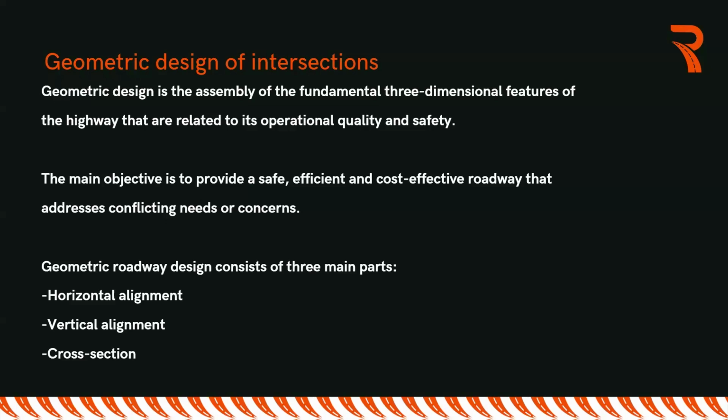And then, of course, you need also to address conflicting needs or concerns. A concern that comes along, especially in intersection design, is the land. What amount of land do you have available at that intersection? What road users are going to be using that specific area? How are you incorporating motorized and non-motorized traffic at that intersection? How are you taking care of people with disability at that specific intersection?